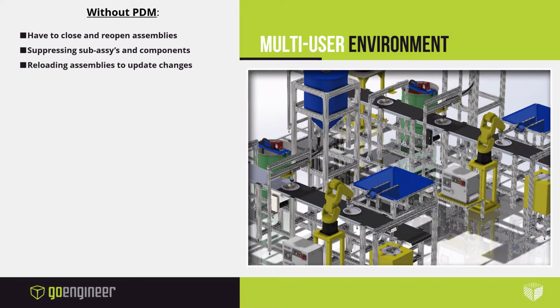We did learn some tricks though. You could suppress a subassembly, or suppress a component, and save the assembly. They could open it because since it's suppressed, it's not loaded in memory. We're not grabbing it or anything. Then somebody else could grab it. But once again, there was this big halt. There was a save, and honestly, John, some of my save times back in the day were like 20 minutes long. So this wasn't something quick and easy to do, regardless.